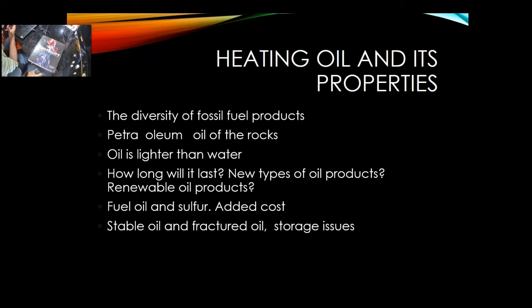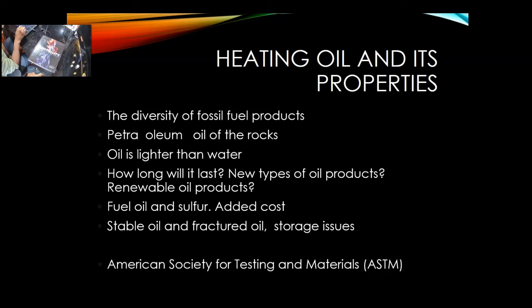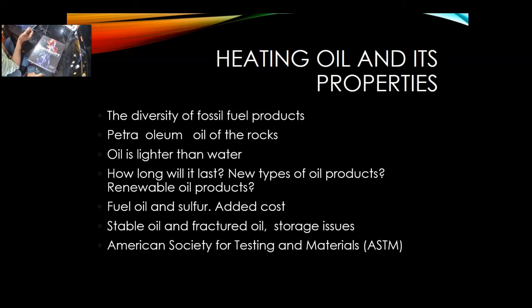What they were saying is that fuel oil is very stable in its natural form, and once you take the sulfur out of it, it becomes unstable. That's why storing oil for a long time makes it decompose into something else, meaning that you cannot store oil for a long time if you have taken the sulfur out of it. The American Society of Testing and Materials gives the standards for how to store oil and what the properties should be to be able to sell these oil products.